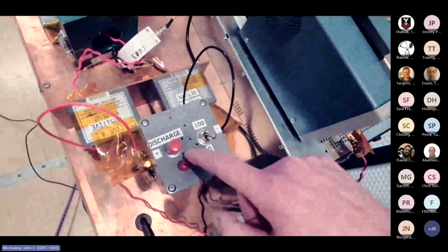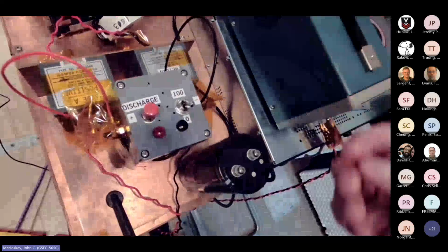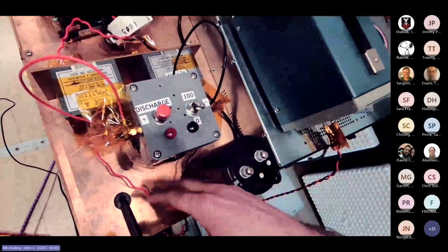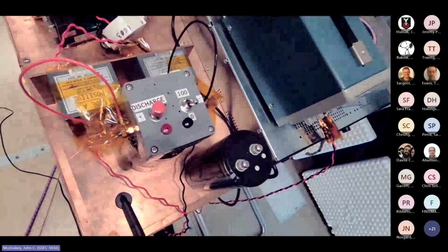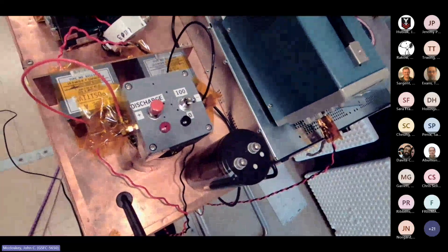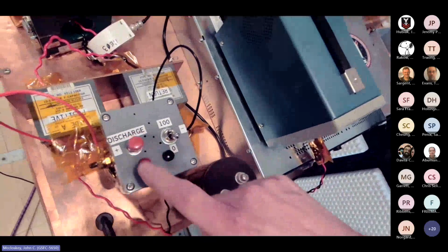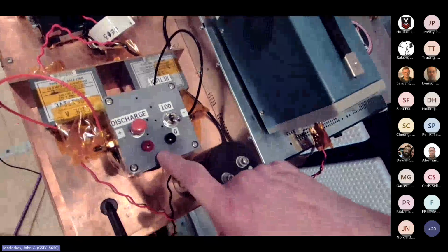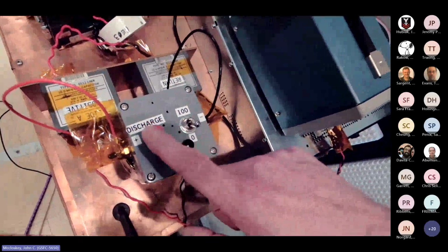And then there's a discharge switch kind of on the opposite end of things. When you turn off your EUT, if there's not a sufficient leakage path to discharge 30 volts from a 10,000 microfarad capacitor, that 30 volts can stay there for a while. And so just hitting this button, I think it's a couple K. Again, nothing real magical about a specific value there, but on the order of a couple K, you hit this button.